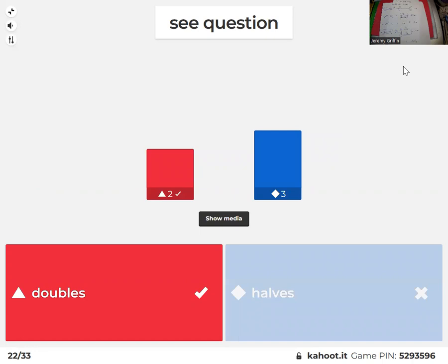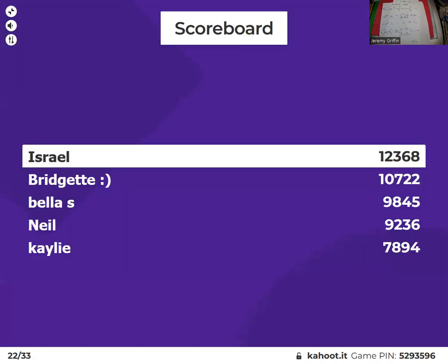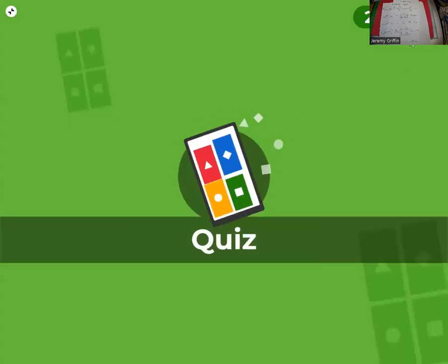All right. So if you picked the blue one, you probably were thinking series, but because it's parallel, the answer is wrong. It's going to double. You guys remember back in your lab, every time you added on another bulb in parallel, they all maintained their brightness, right? So that's what happened here. So not only does the battery have to supply the first 70 watts, it also has to supply the other 70 watts, right? So yeah, that would double the current and therefore the energy leaving from the battery.